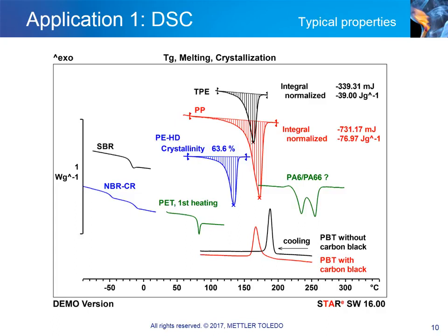Glass transitions are characterized by a step-like change in the heat flow or enthalpy. In the first heating run, the transition is often accompanied by a peak related to enthalpy relaxation caused by aging. An example of this can be seen in the DSC curve of PET. Large enthalpy relaxation peaks only appear in the first heating run, as the heating erases the aging history. The temperatures at which glass transition and melting occur define the usable temperature range for manufactured parts.